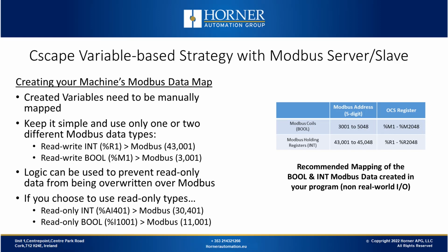If you're concerned about the data being read-only in your equipment and then being overwritten from the outside, you can use logic to prevent that from happening. For instance, if you have a boolean that you don't want to be overwritten by Modbus, if you just use it as a coil in your application and your logic program, then Modbus can't override it because the OCS logic is continuously writing that coil.